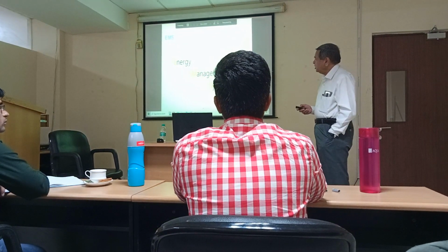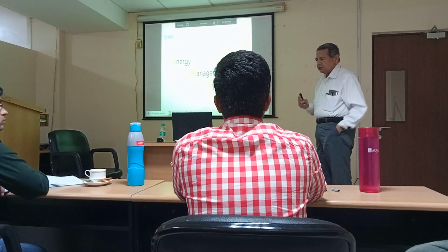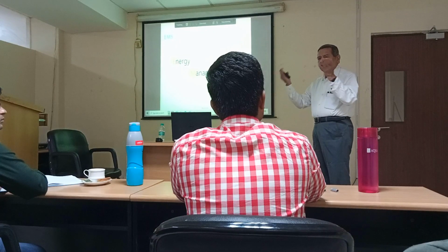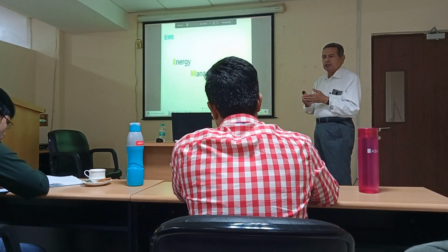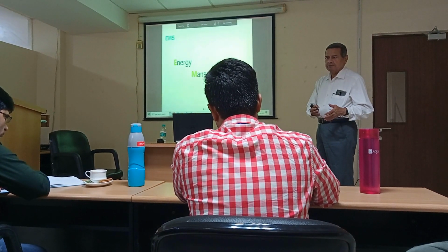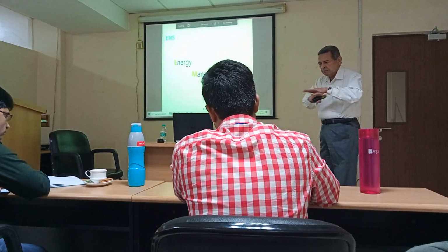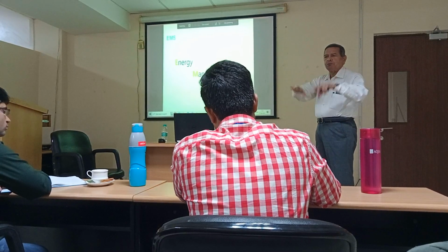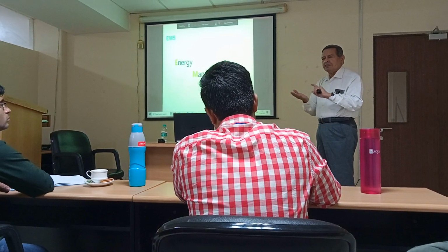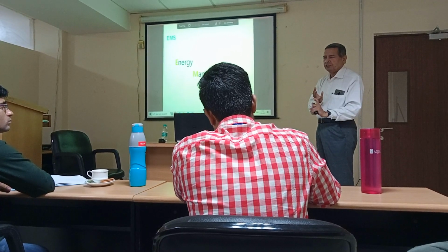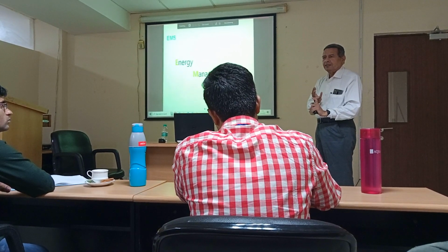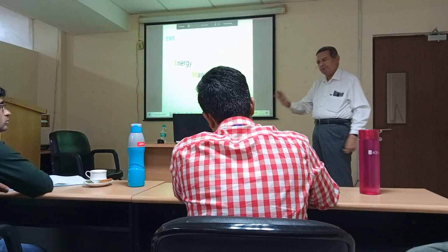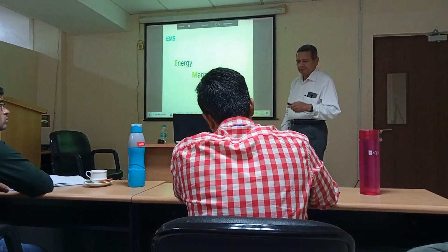Okay. Energy management system is a set of software which sits on top of the SCADA system. The EMS will not work unless SCADA is there. So SCADA is the basic layer. It's like the flooring, and on that you can put a carpet. Really SCADA, and then on top of that EMS. On that you can put other furniture, so there will be other layers also, but I'm talking just of these two layers.